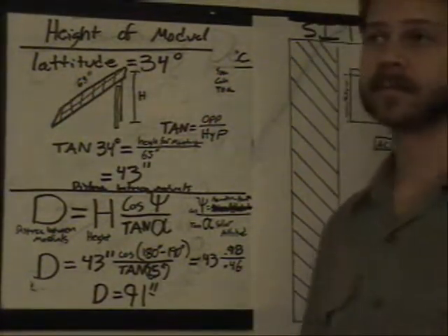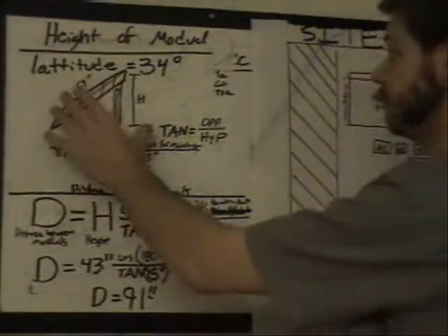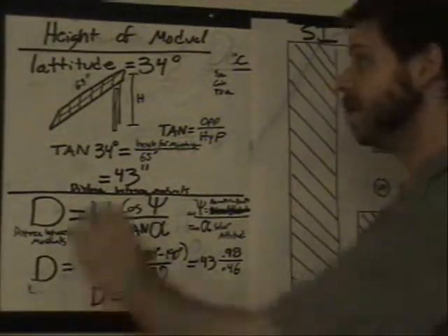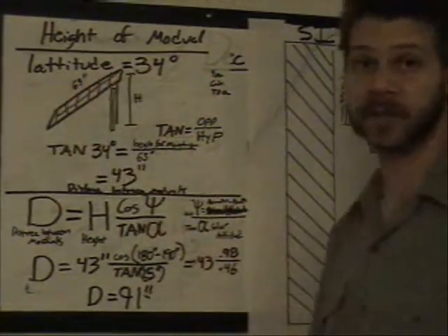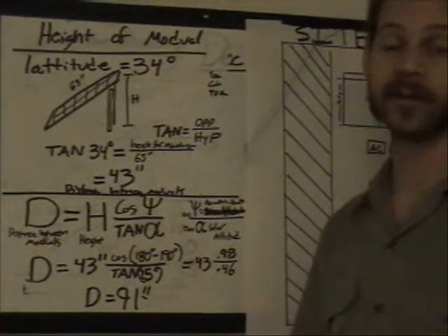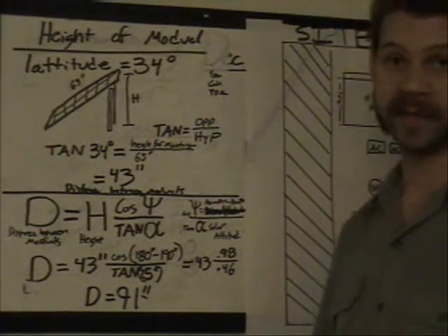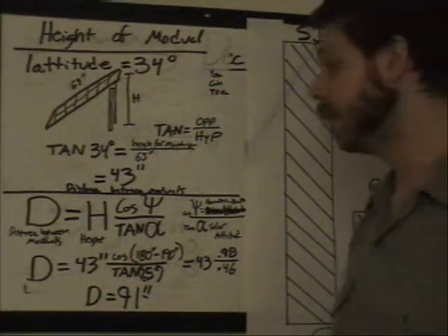That's helpful not only in determining how much shading, but if you have a huge number of modules to go up, these standoffs can actually be pre-cut and drilled before you even drag them onto the roof, saving you a lot of time, saving you working on the roof, and saving you clutter on top of the roof.